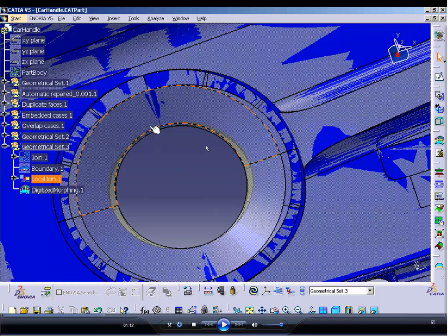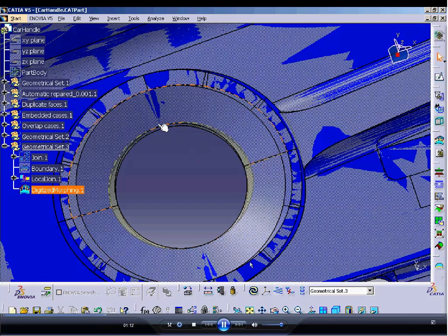It's going to have different shrinkages in different directions. So based off of this criteria, we have a tool called RSO, which is called Realistic Shape Optimizer, that allows you to quickly go in, run the analysis, and take that information from the analysis and bring it back to the part. So in essence, you're going to change the part, you're going to morph the part.